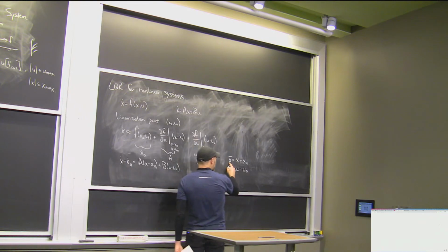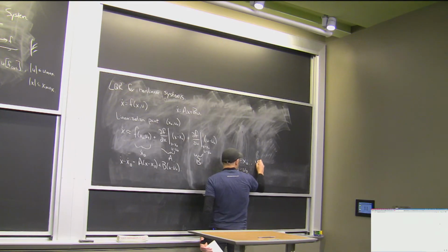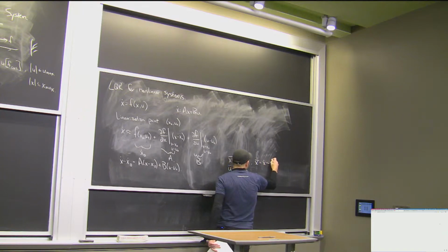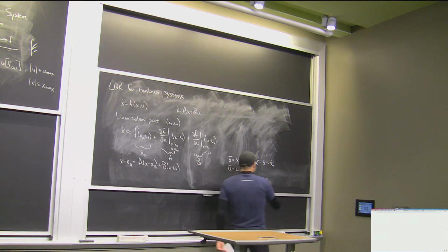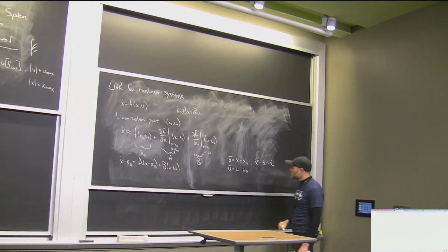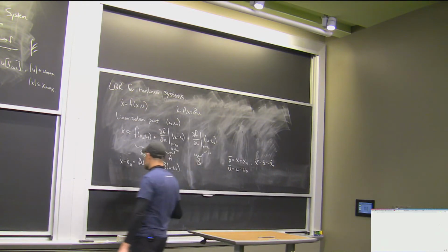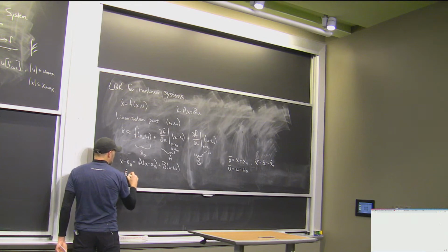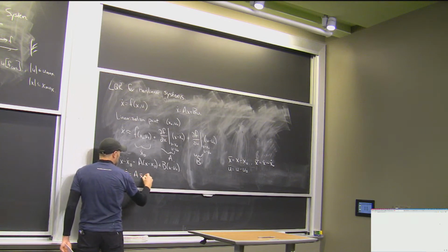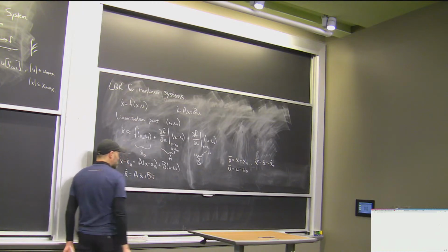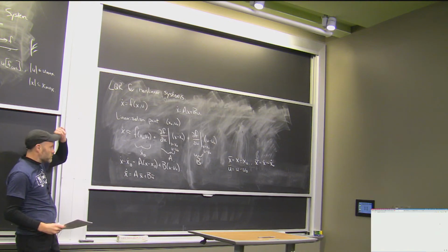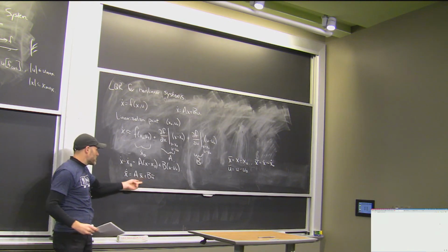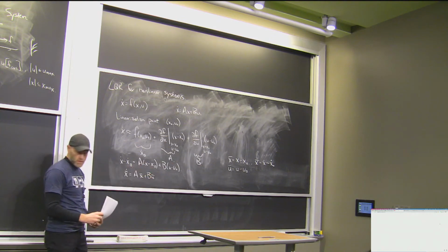And if I were to take the derivative of this new coordinate, I also have that x bar dot is just x dot minus x dot 0. Okay? And in that coordinate system, then I have x bar dot equals A x bar plus B u bar. Okay, so that's how the mechanics of it work. I do have a linear approximation in a new coordinate system around my nominal point.